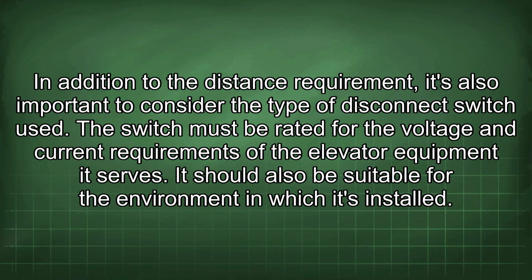In addition to the distance requirement, it's also important to consider the type of disconnect switch used. The switch must be rated for the voltage and current requirements of the elevator equipment it serves. It should also be suitable for the environment in which it's installed.